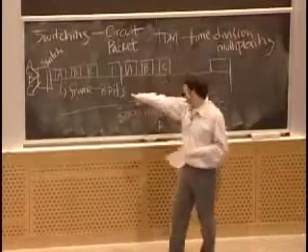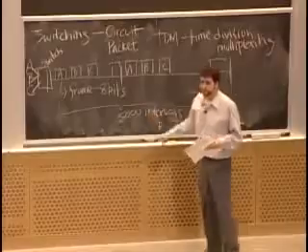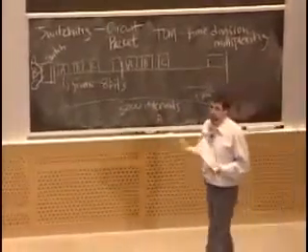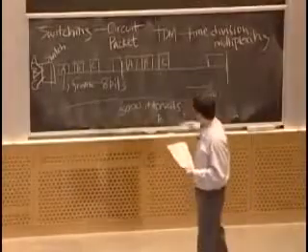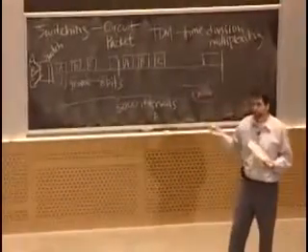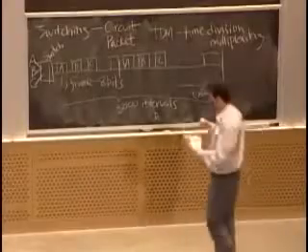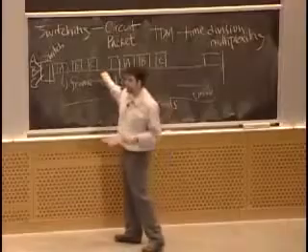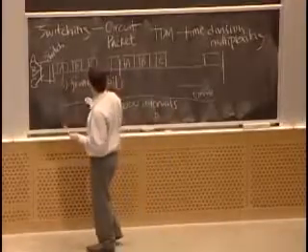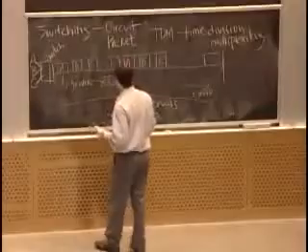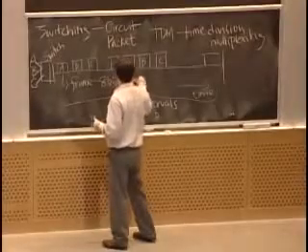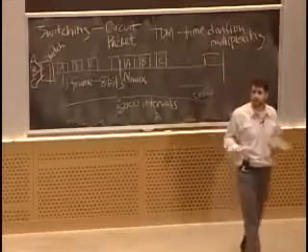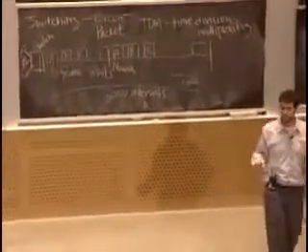Okay, and so what that means is that if each frame is 8 bits and there are 8,000 intervals, each sender can send 64,000 bits per second. And it turns out that 64,000 bits per second is about enough to encode voice at an acceptable level for people. So we can talk about the capacity of this channel by looking at the number of frames in one interval. If we say there are n max frames in one interval, then that specifies the number of conversations that we can simultaneously maintain on this wire.